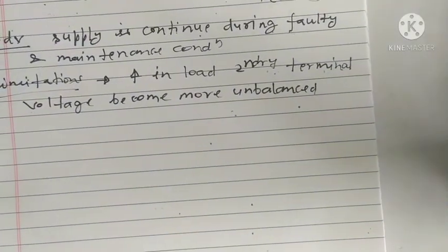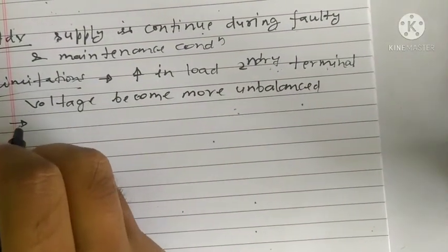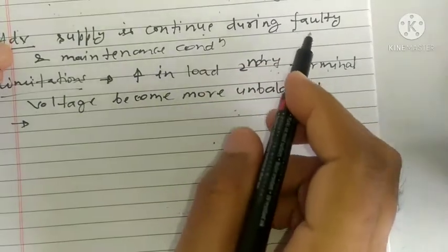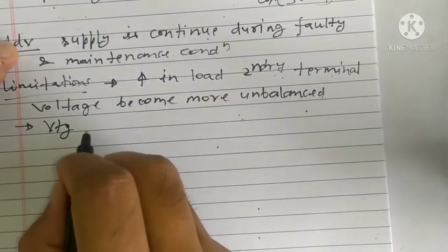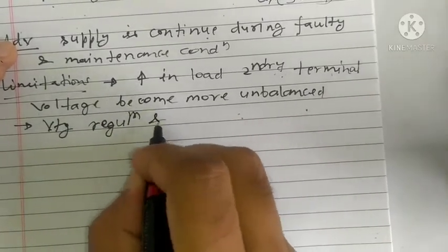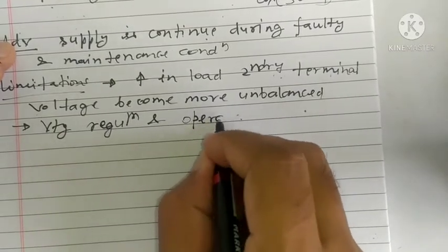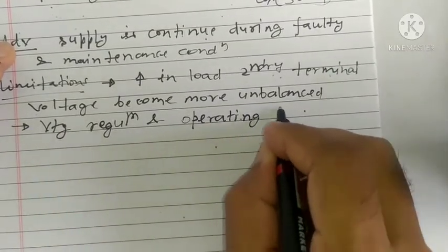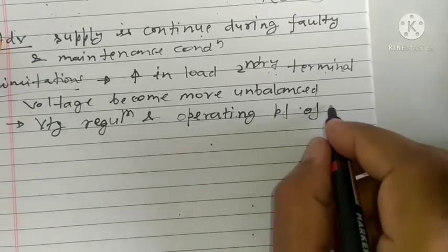And the second limitation is that the voltage regulation and operating power factor, as we have seen for power factor, of both transformers are different.